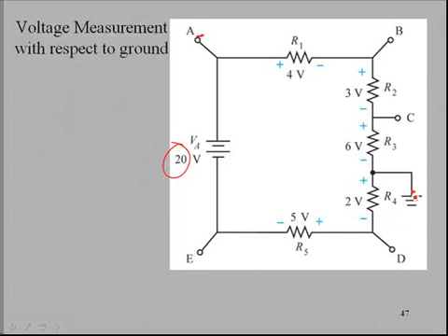And we will certainly see some things different if we measured, for example, point D to ground. So in this case, we're actually going to measure a -2 volts if we have our voltmeter connected. So the common probe goes to the ground and the voltage probe goes to D. We would see -2 here. In this case, if we measured here, we would see -7 volts. Now when you begin using Electronics Workbench, you'll be able to build a circuit like this, and you'll be able to measure those quantities and prove that that is in fact the case.